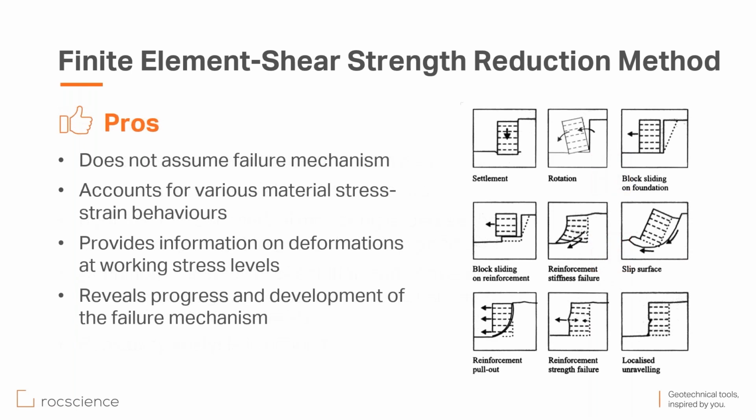Now, the pros for finite element SSR, the main one, in my opinion, is that you do not assume any failure mechanism before solving the problem. So, for example, on the right side, you can see a retaining wall, a supported retaining wall, for example.